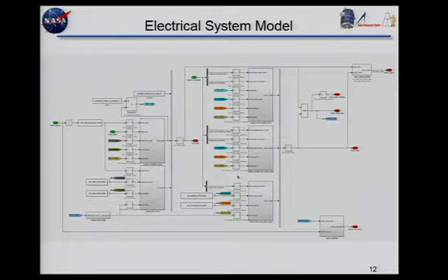The tables for the routing were auto-generated based on the tables from system engineering, and would essentially route the signals across and then recombine them back on the left-hand side into a full vectorized output of the state of the switches that match the input state and match the input order. So that was all done automatically. So once this was set up, we didn't have to worry about it.